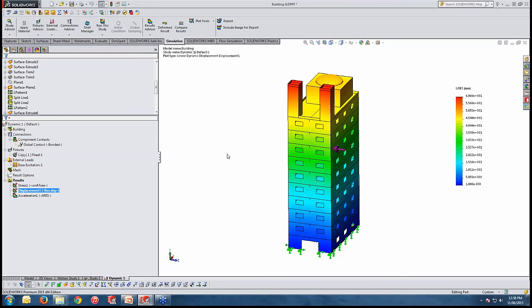Well, when you're creating a nonlinear dynamic study, you have the time varying load, and simply with very tiny steps, you have to solve the model. But in so many cases it's not practical, and it is always recommended that such complex structures be run with the response spectrum analysis as a statistical linear dynamic method.